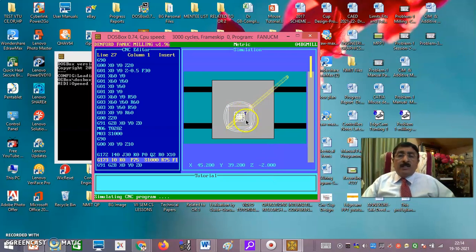You see the tool, this is how the tool moves even on the CNC machine. You can see the overlap also. You can see this is 75, which means 25% overlap will be there between the first successive path and the second successive path. 8 mm is the diameter of the cutter. Now minus 2 is over, then it becomes minus 4. After minus 4, it will go to the home position.